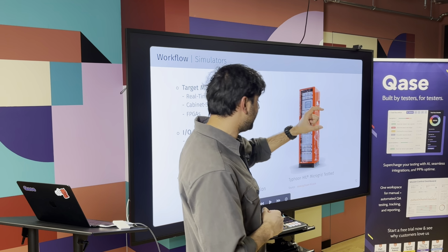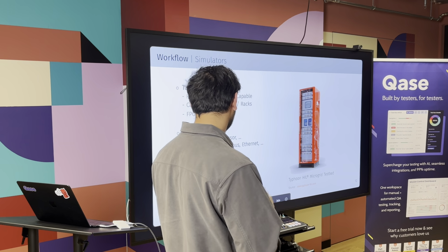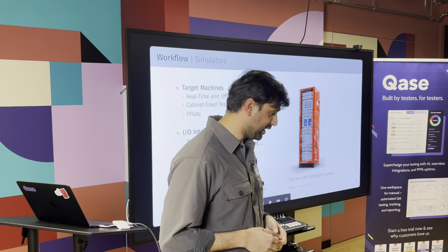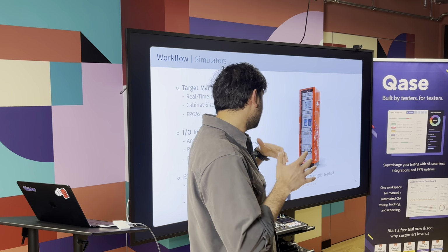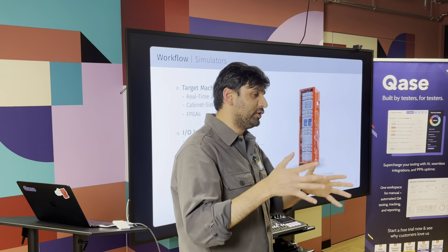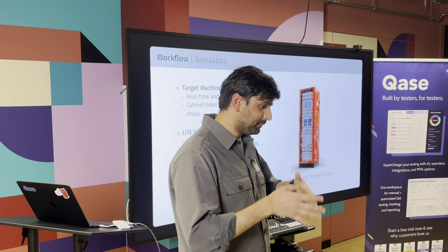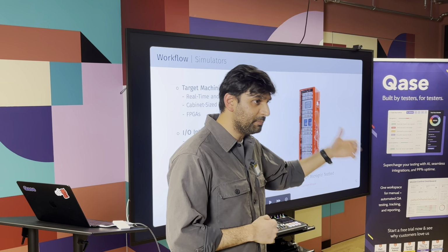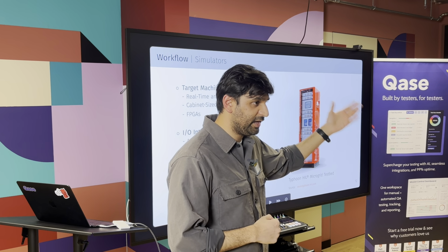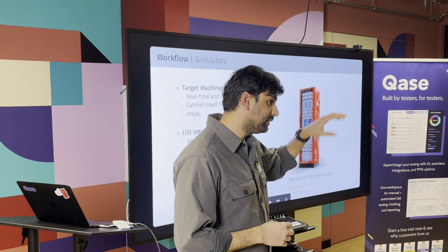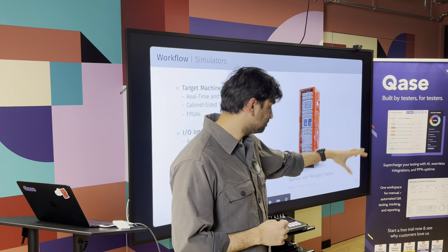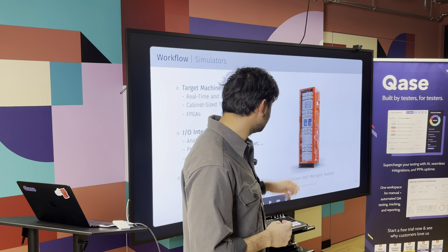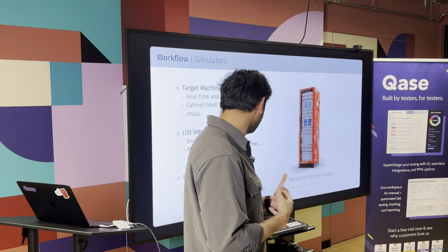And so combining your models and your simulators, you can build an end-to-end infrastructure. You have a block modeling environment. You go from your requirements to your model. And then from your models, you can automatically generate the embedded code in C, C++, VHDL, whatever you want, that will live on your embedded devices, or on the embedded system on your simulator, and then you've got your digital twin.